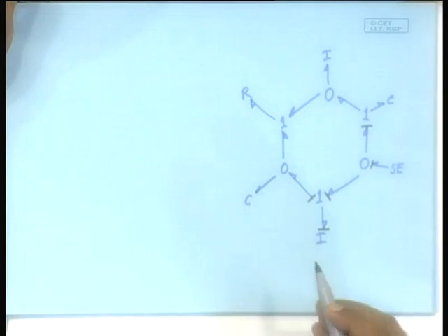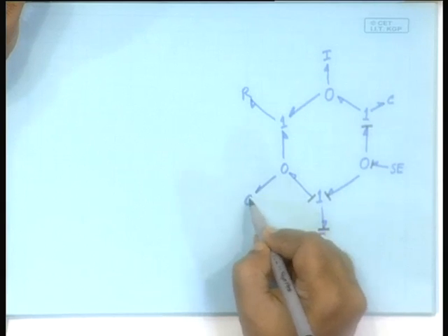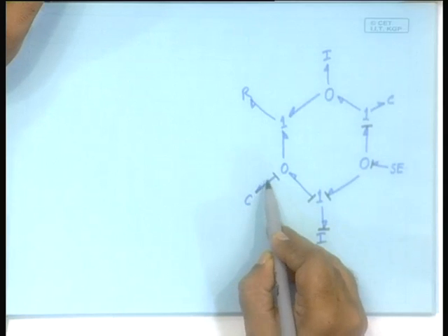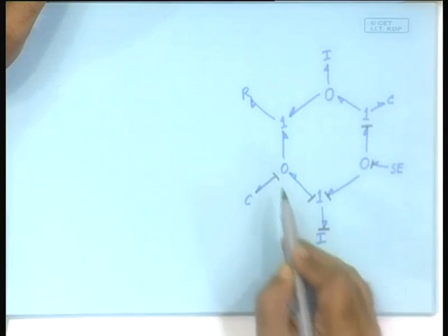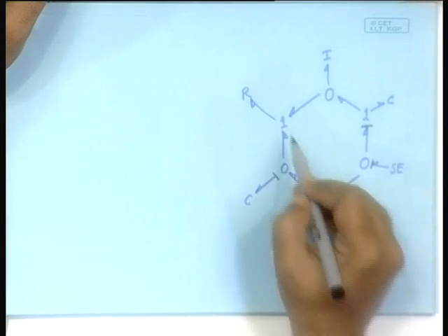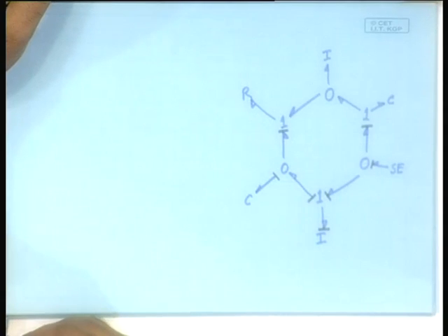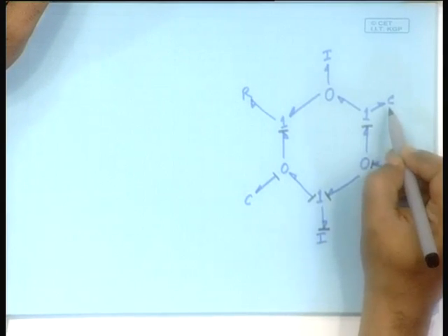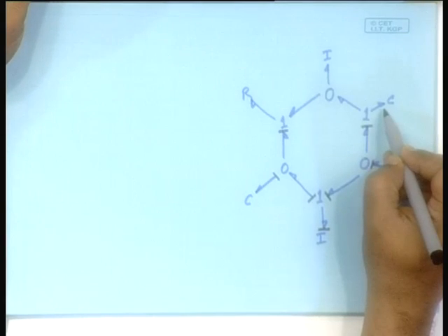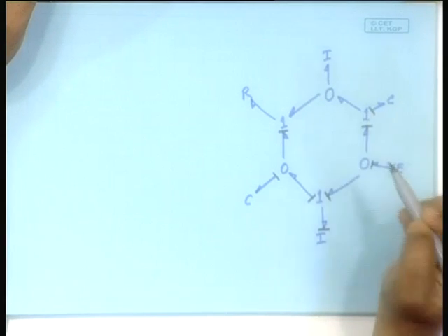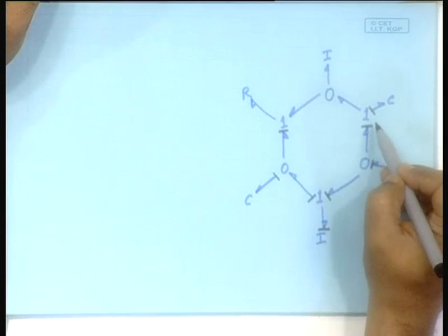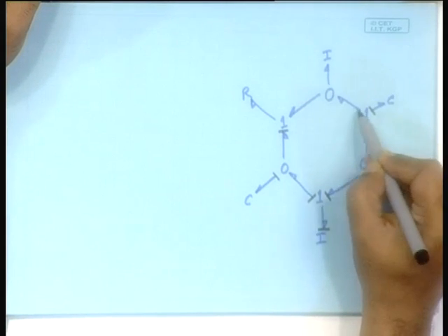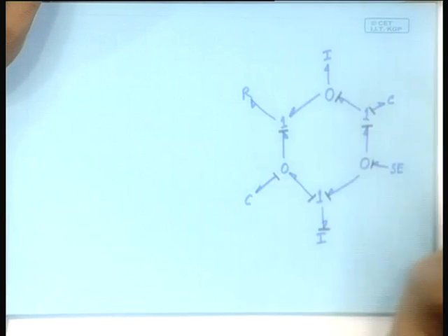As yet these are not causal. So, let me put the causality here. See, its integral causality is like this. So, it is giving the effort information into the 0 junction. The moment it gives, it has to be distributed like this. R will leave out to do later. See, what kind of causality does it have? Its natural causality is like this. So, as yet these two fellows are taking out the flow information, therefore, this bond must bring in the flow information like this.